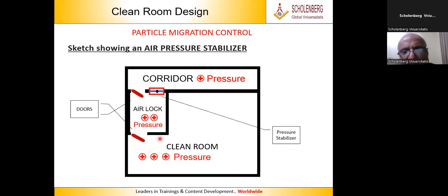So these are 3 pluses and 2 pluses. You see that carefully? If I open towards the 3 pluses and I move away, the door will close because the pressure out here is more than the pressure of the airlock. The door will close. There's no chance the door will not close. Okay. So how do you place the doors?